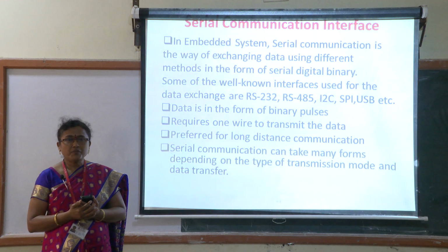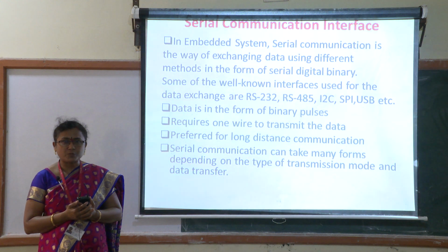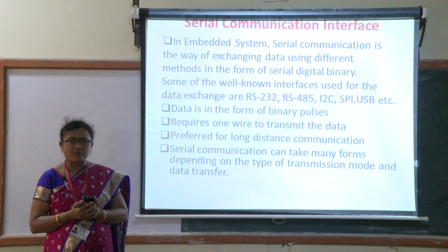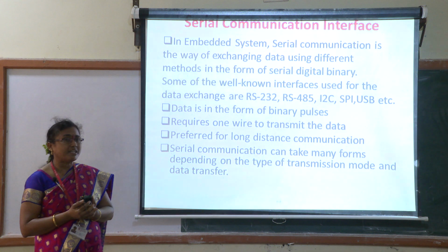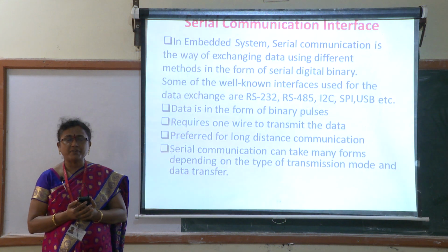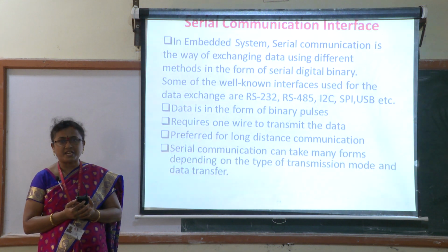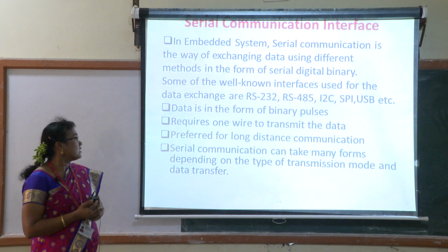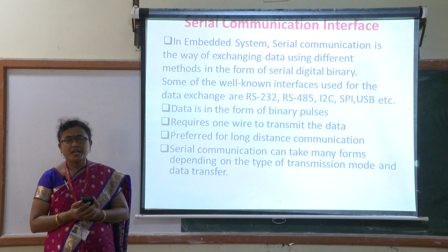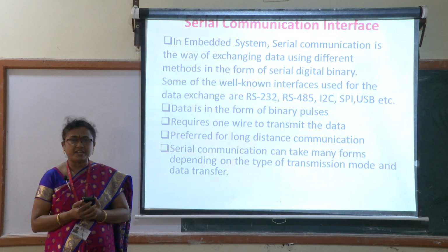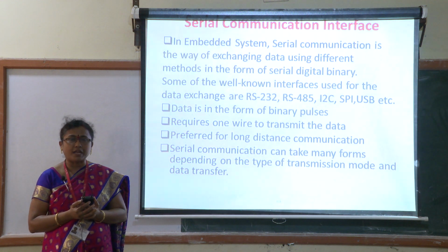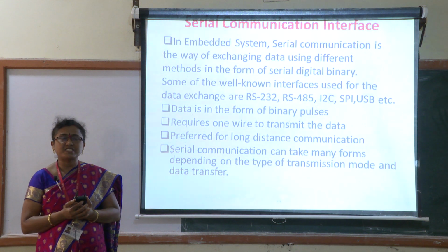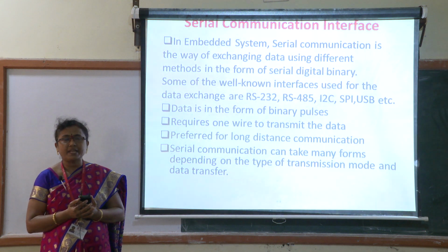Now before getting to I2C bus or USB or whatever it may be, I have to give a little understanding of the concept of what serial communication is, what the communication bus system is, and why it is required. Serial communication means I am going to transfer the data from my system or laptop to the connected device character by character.